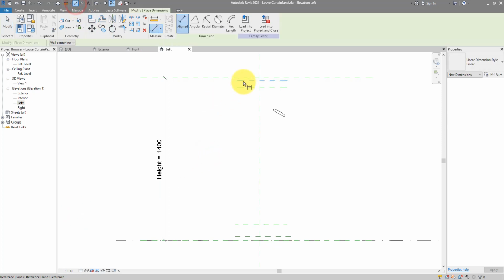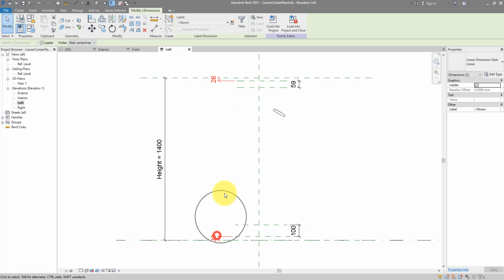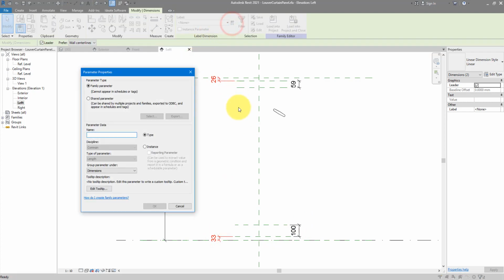It's time now to make our additional dimensions. So one here, the same one below, and 2 more on the other side. I can now call the smaller ones boundary offset. The reason being, sometimes you have mullions along the boundary of this panel, and in that case, you will want the panel to step back to make space for those mullions before the panel geometry can generate, and this parameter will let us do that.